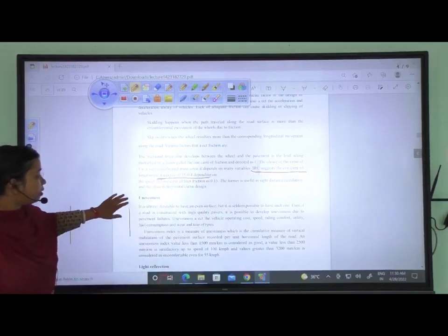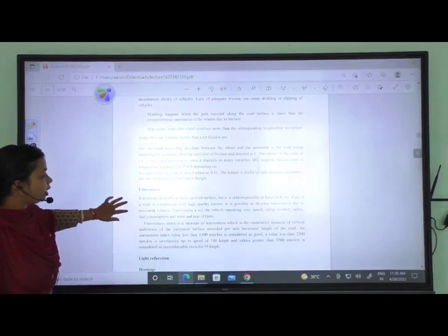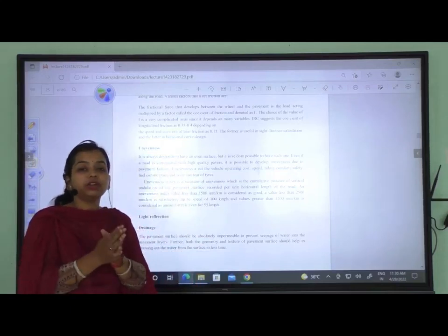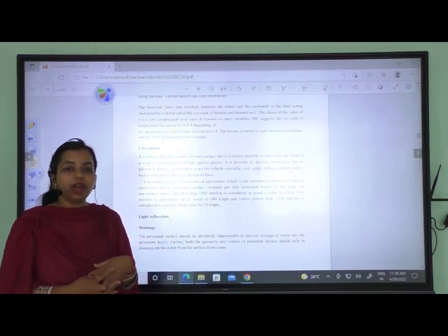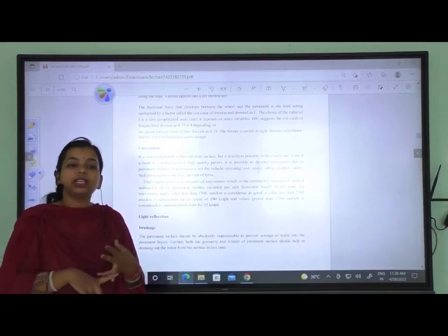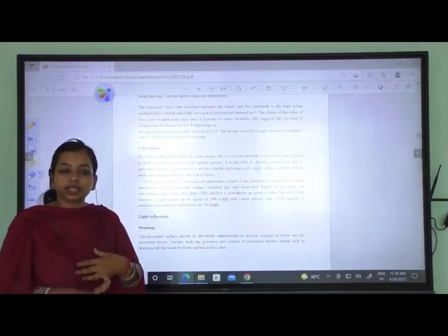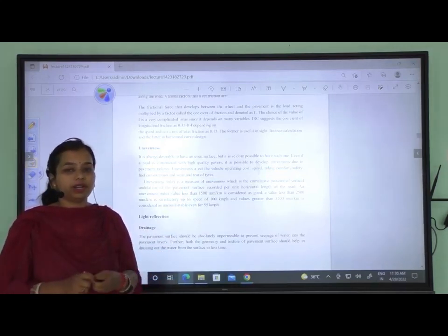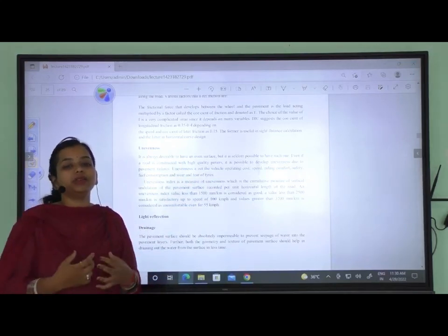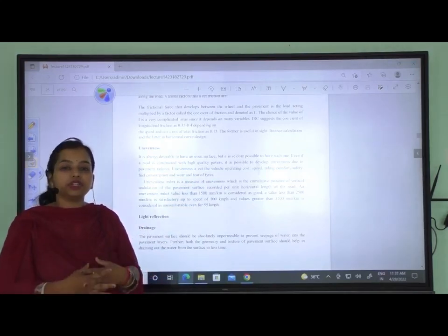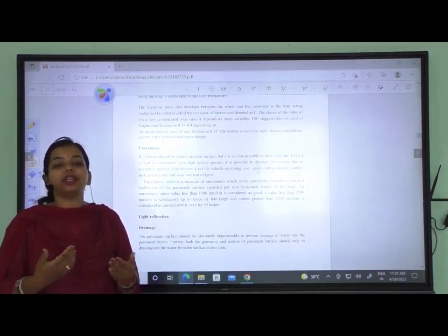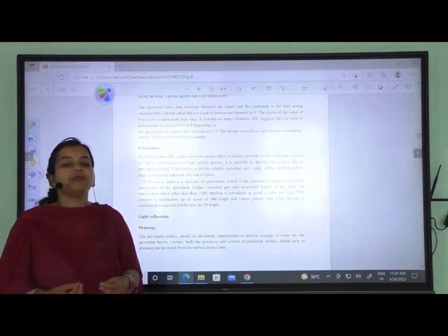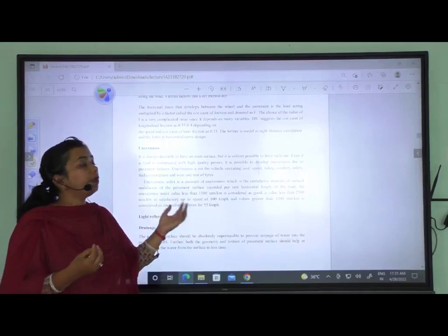So these are the characteristics if you are elaborating a geometric design of a highway. You need to first specify what type of road and what type of construction you are doing, either a national road, a state highway, a major district road, or a village road. That's the important thing. Then you rectify what length is given and what type of friction, what volume of vehicles is traveling on the pavement surface. That thing is important.